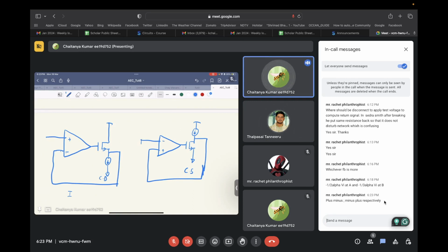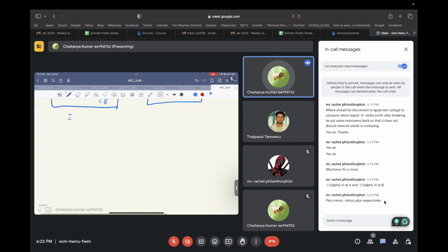Irrespective of whether it has the macro model of the op amp, or it has transistors, or a mix of both, in every case there are two principles. First, cut the loop at a high impedance node. Second, give some voltage and see what sign changes as you traverse through the loop. For example, if there was a complete circuit instead of a macro model, let's say you had this.